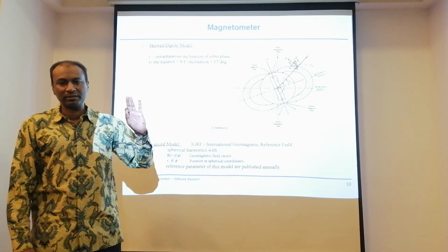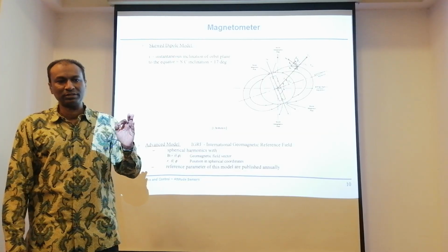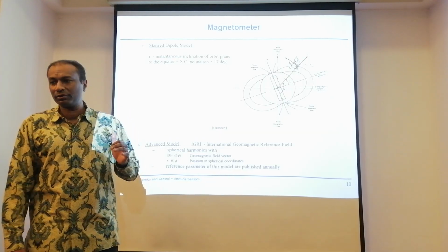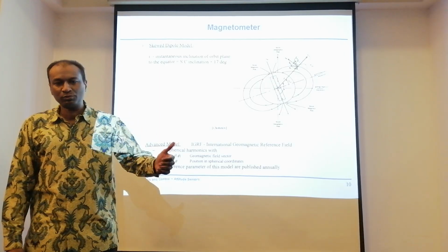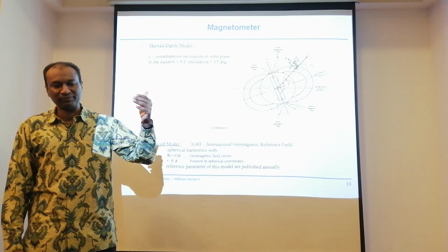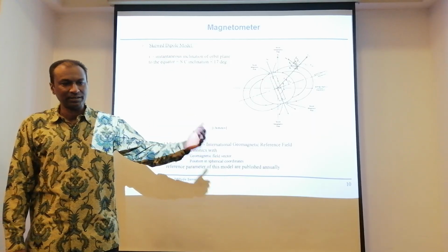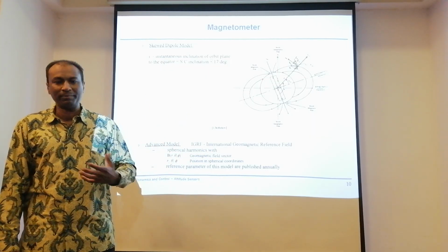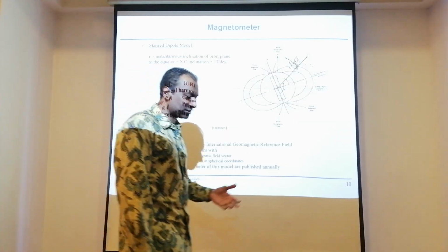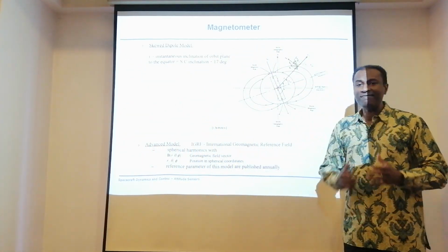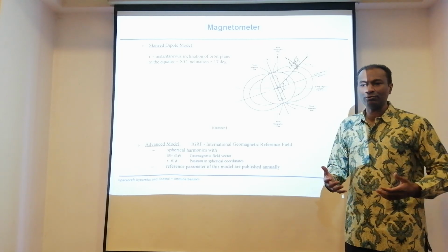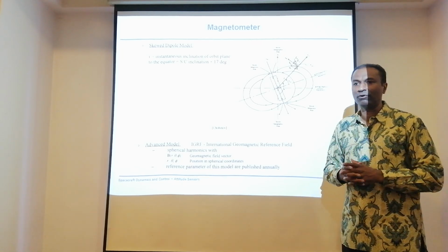Now, just remember, if you want to do attitude determination and estimation, the IGRF model is what is desired. You can't get away with a simple model. But for attitude actuation, prediction, and the disturbance calculation, you can use a simple model, because what matters is the maximum disturbance, or the worst case. In this case, every single moment we need to know how this magnetic model is evolving.